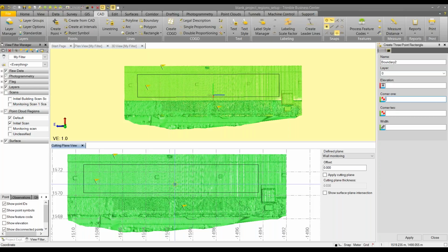David, your boundary for a projected surface object, you're drawing it in the cutting plane view on the same plane definition that is required, correct? Yes. In order for the surface boundary to be applied to the correct surface, it needs to be in the matching plane definition.